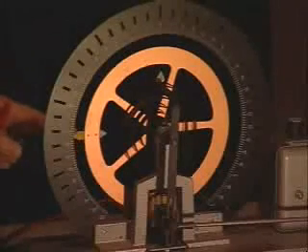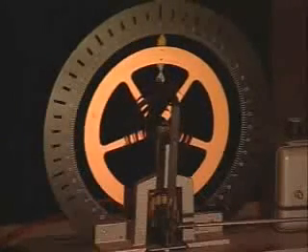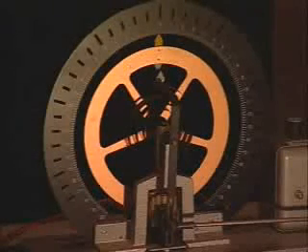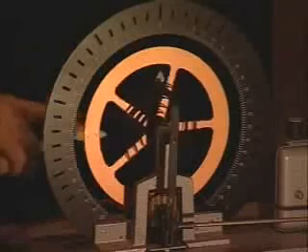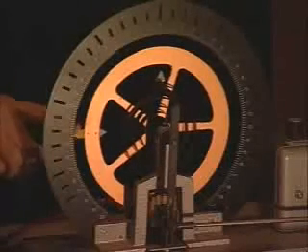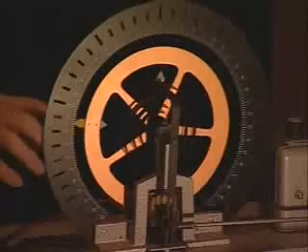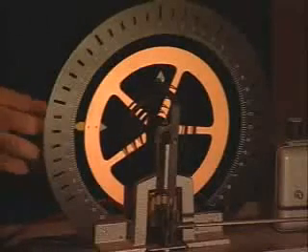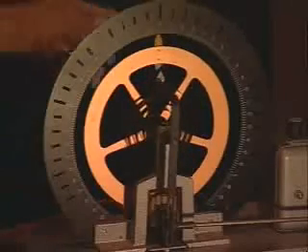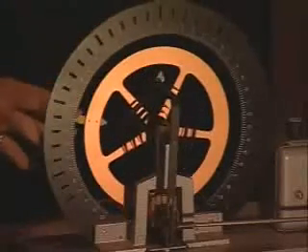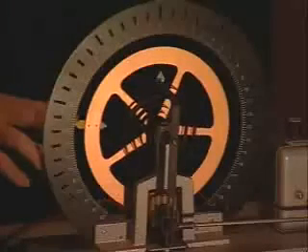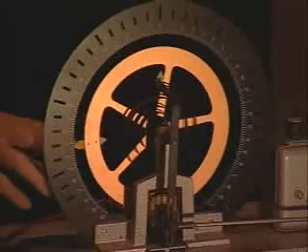3, 2, 1, 0. You see the overshoot? Just a teeny weeny little, that tells you that it is still underdamped because it's not supposed to overshoot since I release it at 0 speed. Of course, if I give it a push in that direction, of course it will overshoot. That's obvious. But if I do it with 0 speed, that solution that we have on the blackboard dictates that it cannot overshoot. I'll show it once more, and you will see the overshoot.